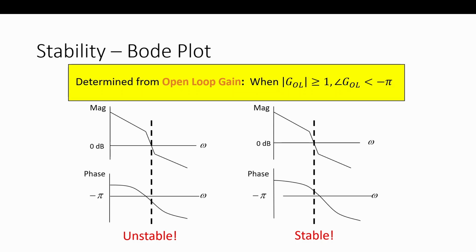If we have low phase margin, we'll get underdamped conditions a lot, uncomfortably close to going unstable if we have variations in parameters. We like to have phase margin. Gain margin is when we cross 180 degrees and we go up here, how much did the gain attenuate? So you get both parameters, phase and gain margin. You can read it from the plot.